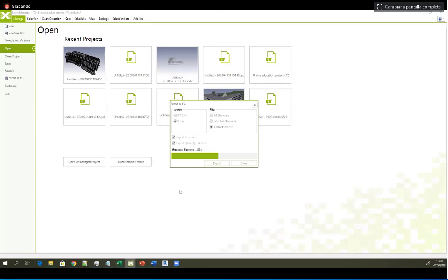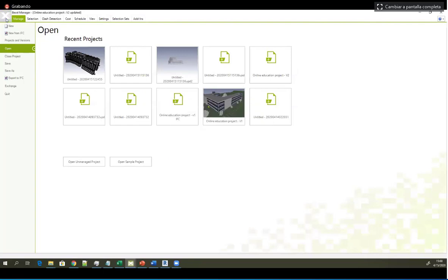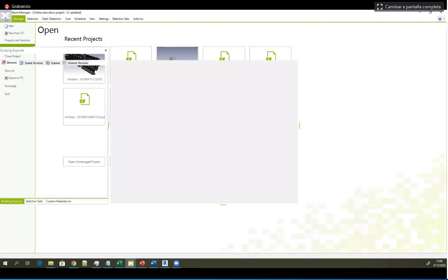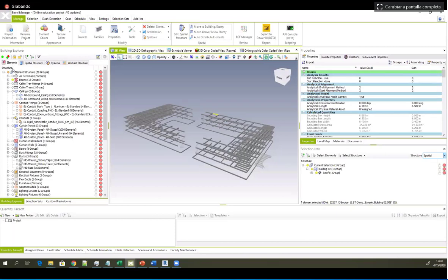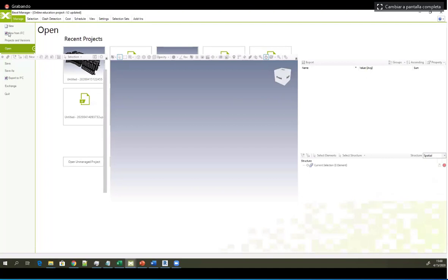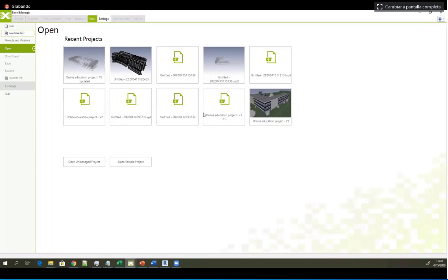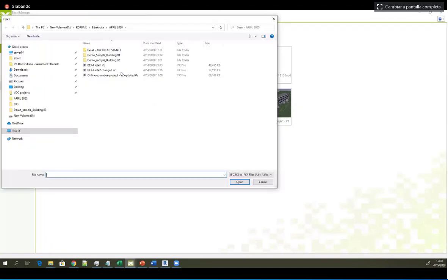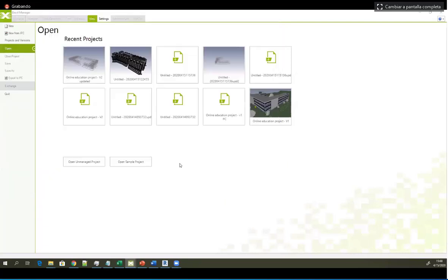So when the system exports this IFC, I'm gonna open it to show you the information are also saved. So now we're gonna close the project and create a new one from the exported IFC. That's the one, hit open, and that's it.